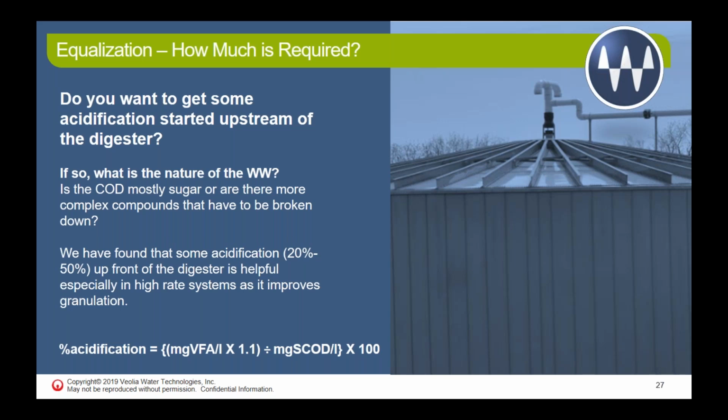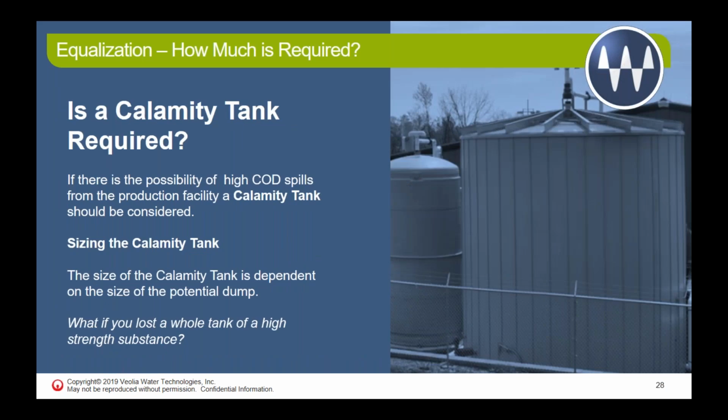And there is a formula for pre-acidification, but basically what we want is a certain amount of time for the biological process to start occurring in the system, so the COD that we have is converted into volatile fatty acids and acidified prior to further treatment downstream.